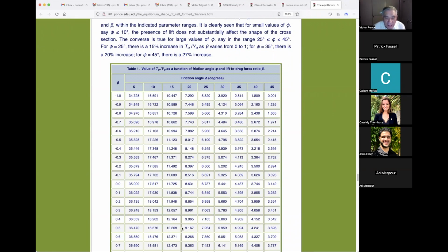So that means that in nature, the friction angles that prevail are going to be more like 15 degrees, if everything is okay here, the comparison, the analogy. Because there's going to be clay. There's always clay out there, silt and clay. The silt also brings the friction angle down. So there's going to be silt out there and perhaps a little bit of clay, and that's going to bring down the friction angle, and you're going to go wider to 10 to 15 and so forth.